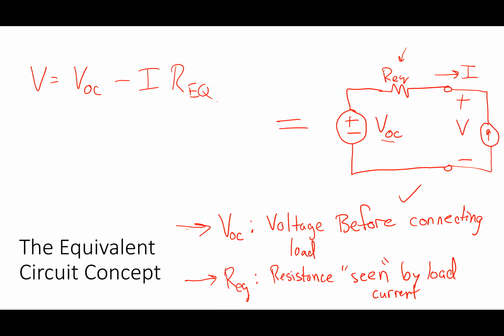I know it's negative because if I short out the internal source, and here's this test source I that I hooked up here, there's going to be a voltage created across that resistance. That drop causes a decline in the voltage.